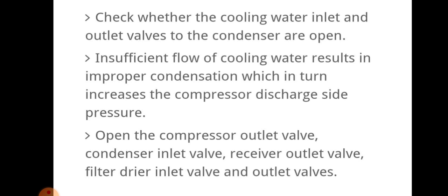We have to open the compressor outlet valve, condenser inlet valve, receiver outlet valve, and filter dryer inlet valve and outlet valve.